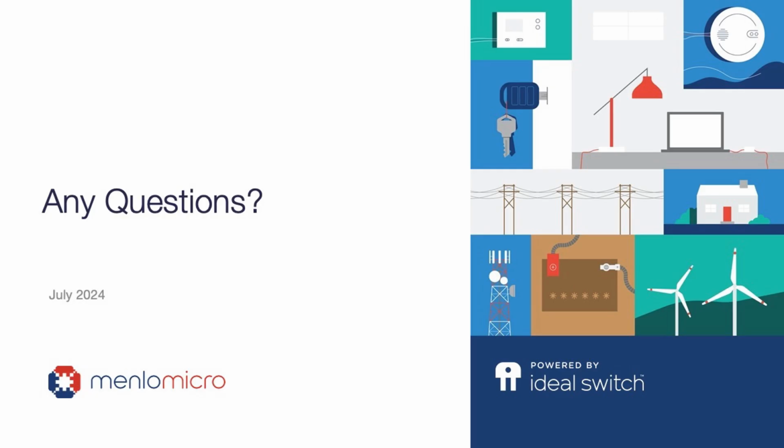All right, thank you so much for that answer, Tom. Can Menlo MEMS switches be paralleled for high power handling? So Menlo MEMS switches at lower frequency applications, typically below a gigahertz, can be paralleled for higher power handling, as well as for DC applications. So MEMS switches have true DC functionality, and in that case, they can be paralleled for higher current handling as well.